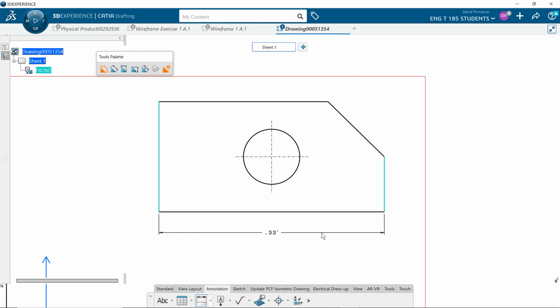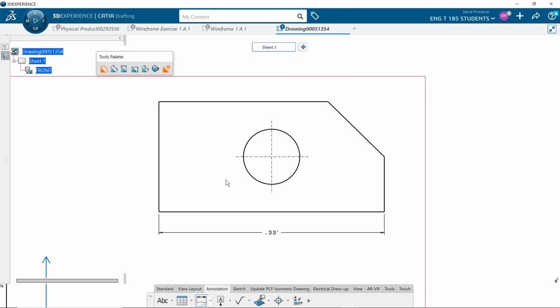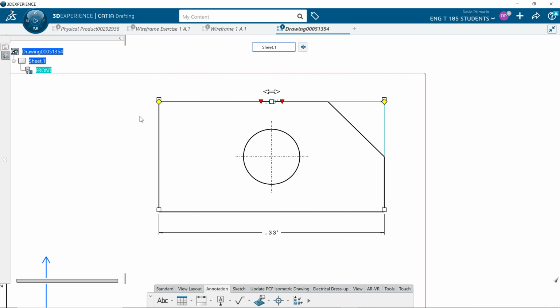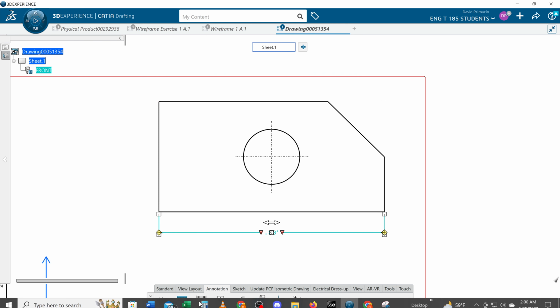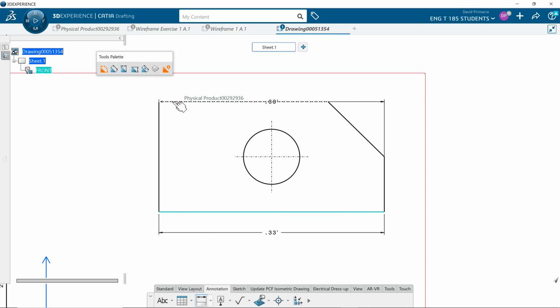horizontal if you grab two vertical lines. So it's dimensioning apart from left to right. Dimension from the bottom to the top. Sometimes I miss. You have to hit Control Z to undo it and go back and try again. Under dimension, select the bottom line, select the top line, which can be a pain because the dimension's in the way. Select that line and move this cursor out.